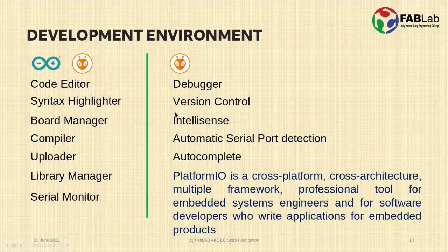The key features which are available inside PlatformIO, and are not available inside the Arduino IDE, are the main reason why I am recommending you to use PlatformIO and VS Code together to develop your projects or applications on embedded systems or Arduino boards specifically. Here the debugger is available inside PlatformIO, and we should learn how to use the debugger tool to debug the programs of Arduino or any other microcontroller.